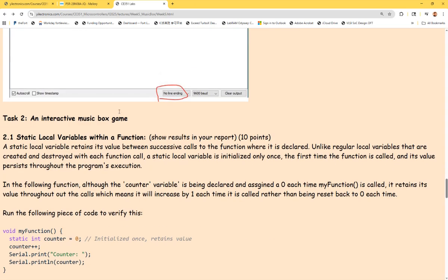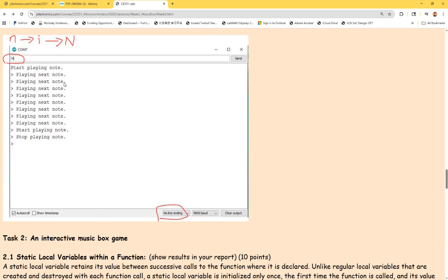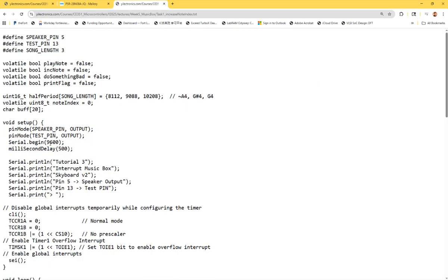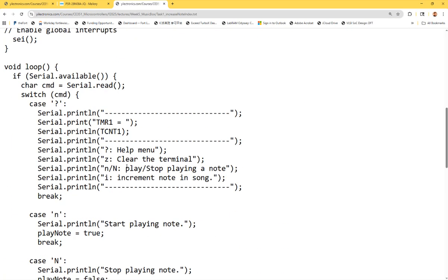So keep in mind, you send a command, it keeps playing until it receives another one. Keep that in mind. So it's basically waiting for the ASCII code or a byte to be received, because every time you type a new letter in the serial monitor, you send it. It detects and receives it, and tries to determine what has been received. So in that case, you need a mechanism here to wait. Or if nothing is getting received, you should skip this whole thing.